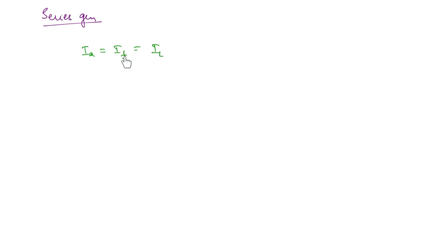Then what will happen to field current? Field current is also 0. So then there will be no internally generated voltage, and if there is no Eg, then there is not going to be any terminal voltage. So you can write here, at no load, that is when IL is equal to 0, the internal generated voltage is equal to 0 and Vt is also equal to 0.